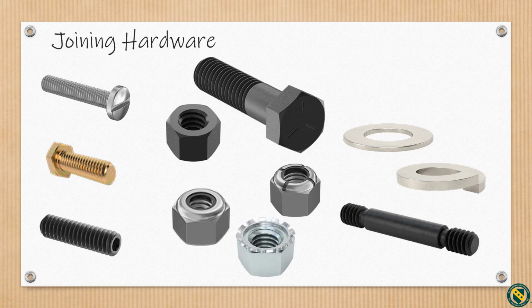The screw thread, often shortened to thread, is a helical structure used to convert between rotational and linear movement or force. A screw thread is an inclined plane wrapped around a cylinder for a straight thread or a cone for a tapered thread. A set screw is a headless threaded fastener that is typically used to hold a sleeve, collar, or gear on a shaft to prevent relative motion.